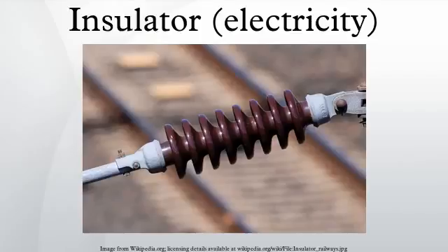Strain insulator. A dead-end or anchor pole or tower is used where a straight section of line ends, or angles off in another direction. These poles must withstand the lateral tension of the long straight section of wire. In order to support this lateral load, strain insulators are used. For low-voltage lines, shackle insulators are used as strain insulators.